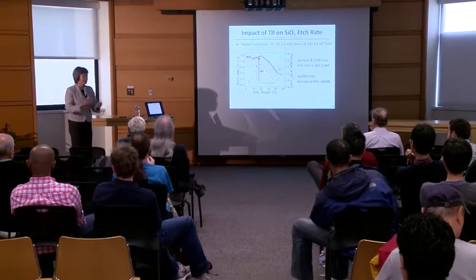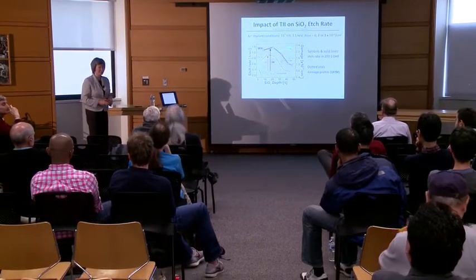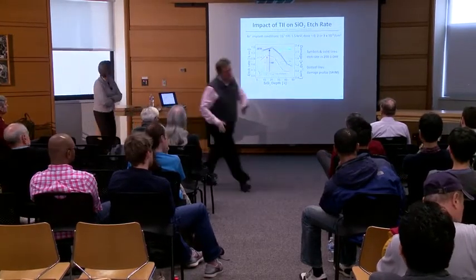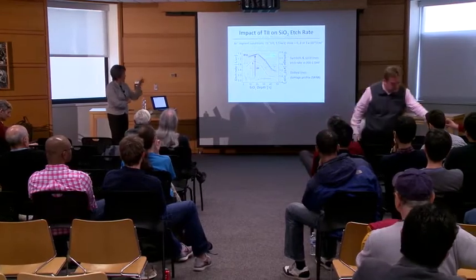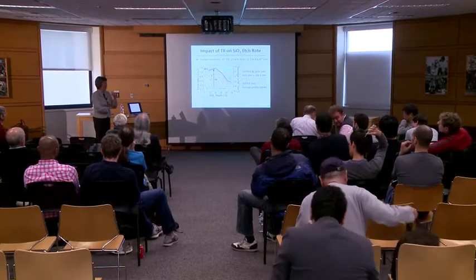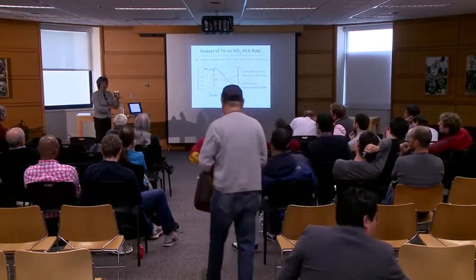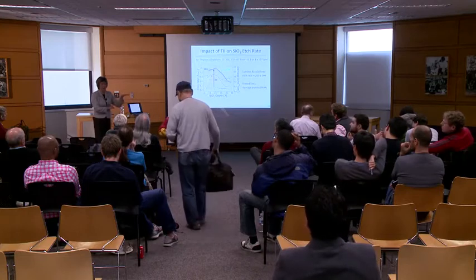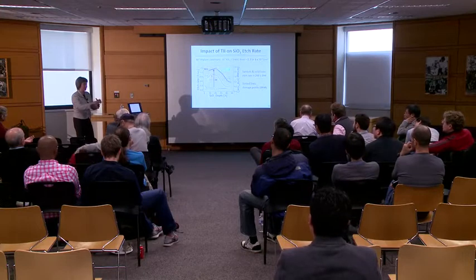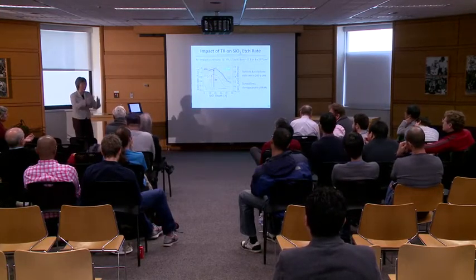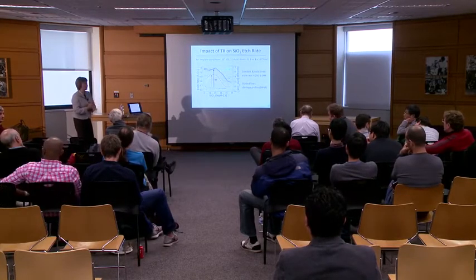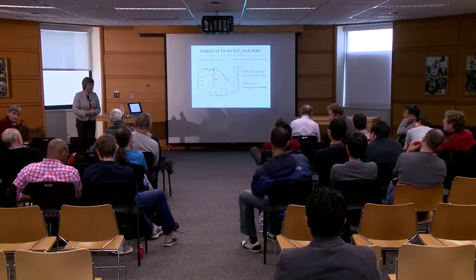Yeah, the argon, I think you can easily anneal out any damage. Okay. I forgot to put a slide here, but what we did here was a thermally grown oxide. Of course, for patterning metal layers, you don't want to have thermal oxide. So we have looked at spin-coated silicon, carbon, oxygen compounds, and we can get similar effects. So you can spin-coat the hard mask and cure it, and then use it to pattern the dielectric layers to form the metal lines. So that's where some materials development work is needed.